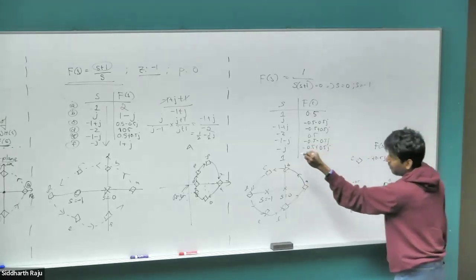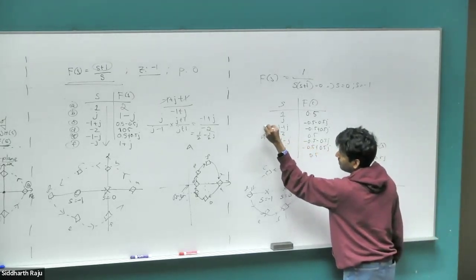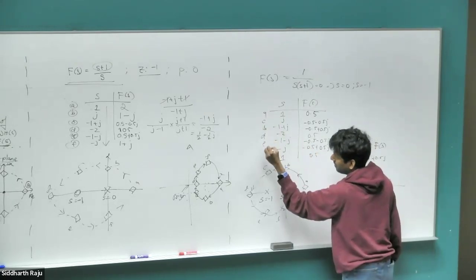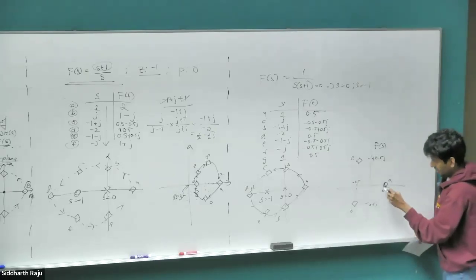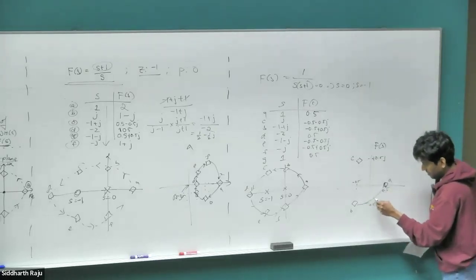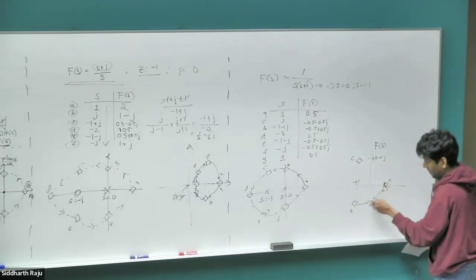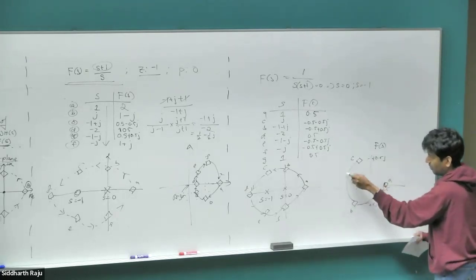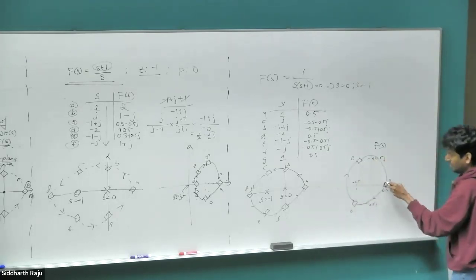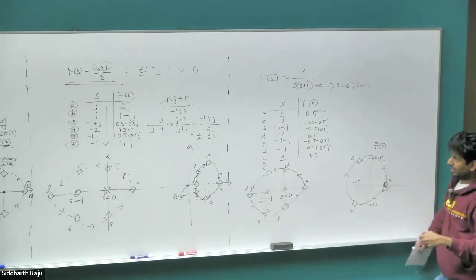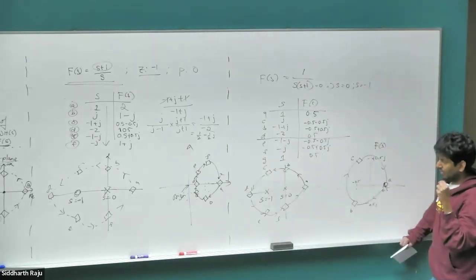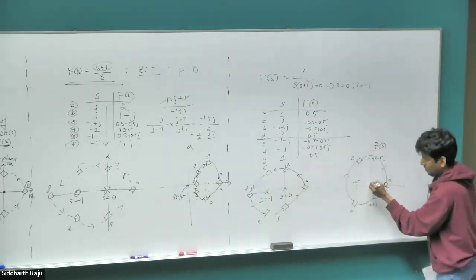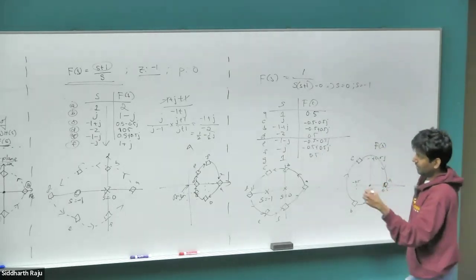And then if you look at where point D goes to, we end up back where we started. Right? So we did a loop like this. So we are going anti-clockwise there, but on the f of S plane, it starts to go clockwise. And we end up right where we started within half the data set. So we have encircled the origin once already, and let's continue the process.